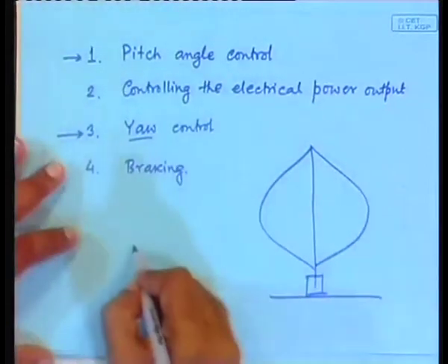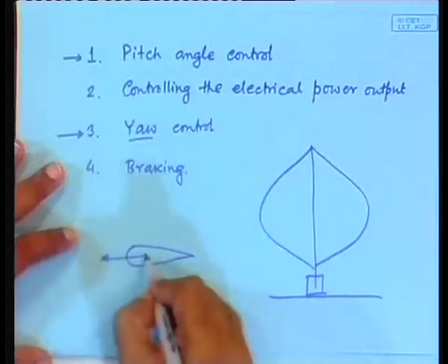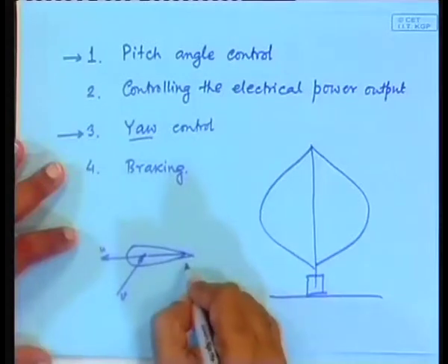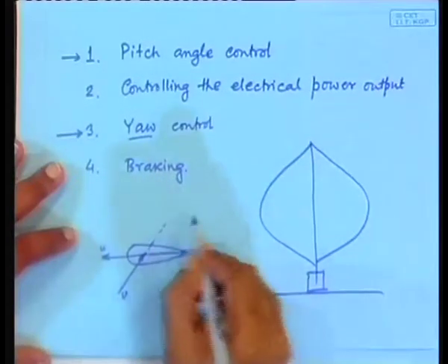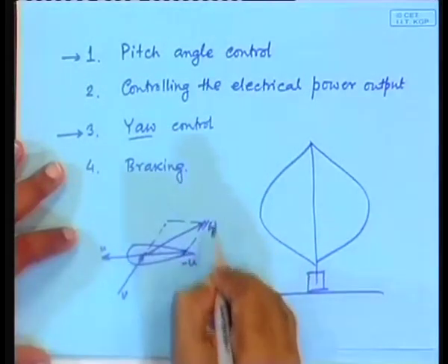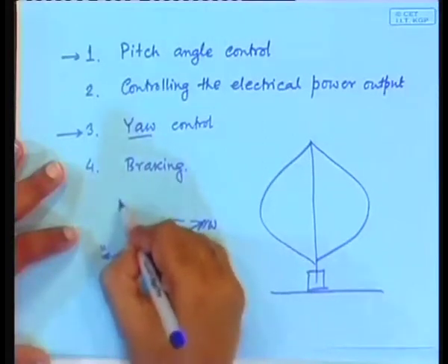That means all the time you have the force created like this. This is moving this way. So, this is your u, and there will be some kind of a v, and you have to draw the parallelogram by completing with minus u. So, you have got this, and you will have the speed, and this is the Fd and this is the Fl,